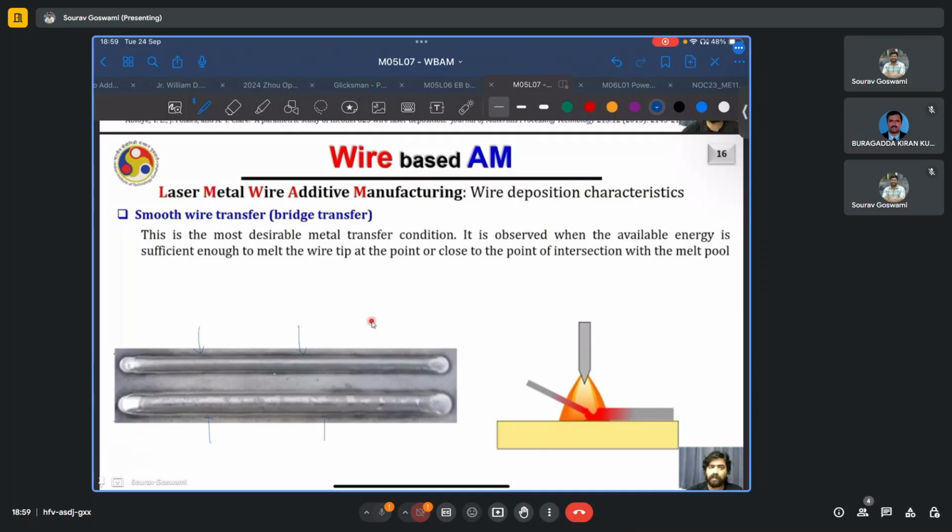Often another type of defect which you will see is because of the process instabilities at the start and end of the deposition process. In the beginning, there might be some bulging or balling, and in the end, there might be some over or under deposition. But the middle region is smooth. Also, typically, it is said that it takes around 3 mm for any melt pool to be stabilized. And after this length of 3 mm, we may expect to see continuous and smooth tracks.